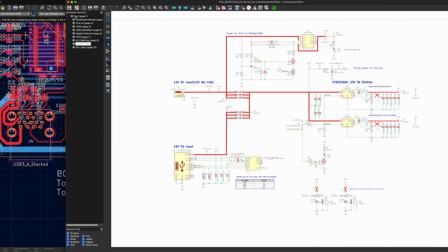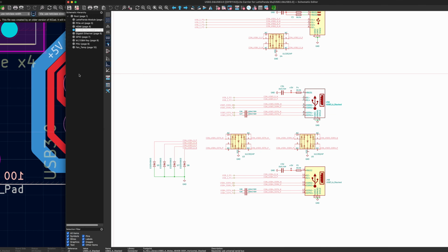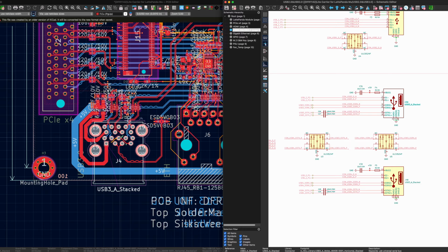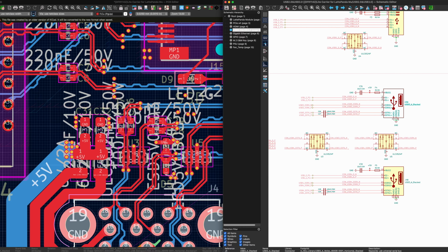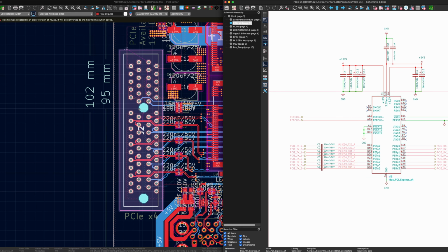In the final section, you'll translate the schematic into a physical PCB. You'll define the board outline, select the number of layers, perform impedance and stack-up calculations, and then you'll move into placement and routing, applying all the high-speed design principles you learned earlier.